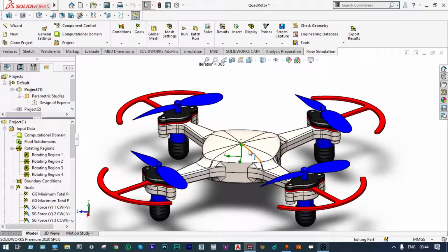Instead of stopping it here, we can do something else, like we can go for some kind of parametric study by varying the sizes of these impellers, and also we can do something like by changing the different rotations of these impellers, we can have different set of net thrust. And finally, from these things, we can have an optimization of dimensions of this impeller, and even we can have an idea of minimum rotations of this impeller. Okay, so this is all about today's analysis.